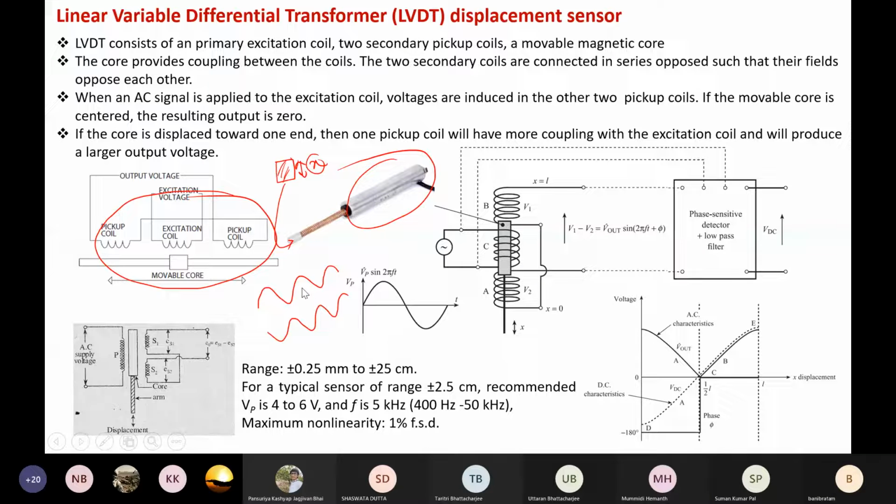So if you look at the waveform on some oscilloscope, then both will look like sinusoidal. So you will be confused whether it is positive or negative, because if you see both the signals separately, then you cannot understand the phase, because in order to understand the phase, you have to compare it with respect to some reference value. So this particular concept is not that convenient. Convenient means looking at the waveform on the oscilloscope, that is not the convenient way.